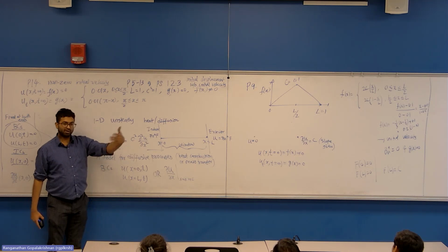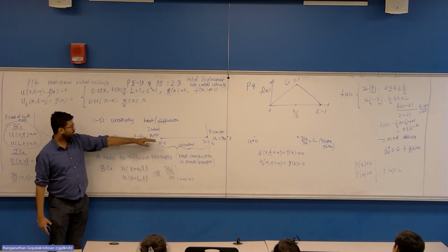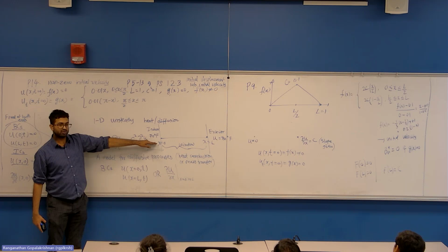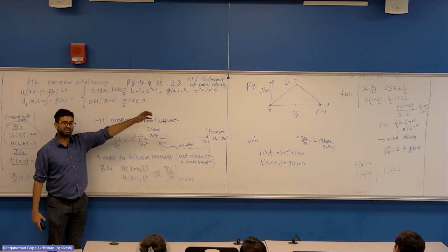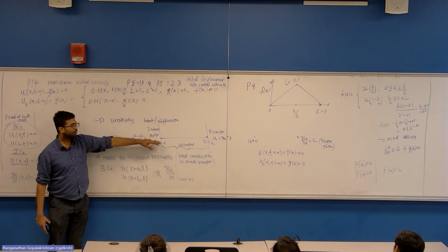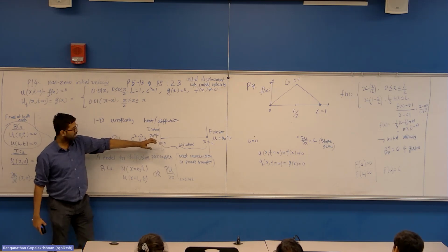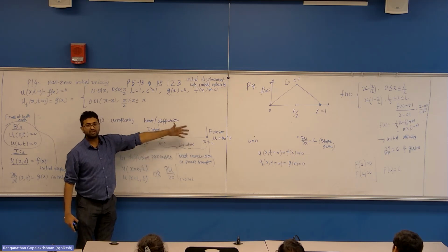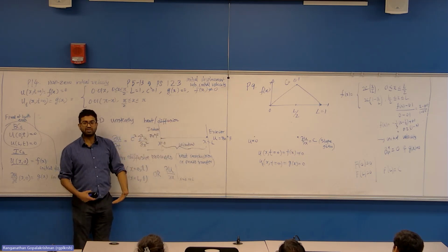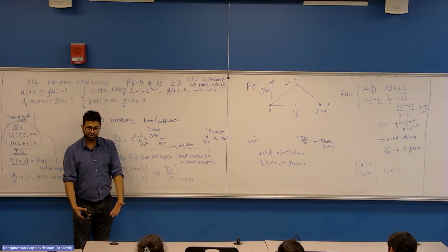You need to have a feedback loop so that you can vary the heat flux suitably to hold it at a certain temperature. The heat flux has to modulate the changes that are going on to hold it at a constant value. If you specify heat flux, depending on what medium it is, at what rate the heat is removed, you're going to have some temperature that is going to come out of your solution.